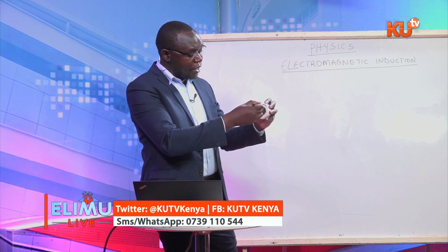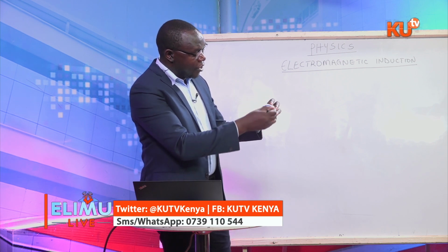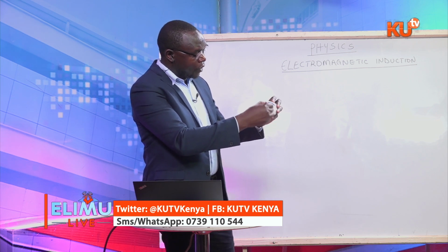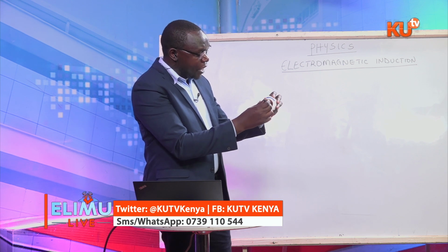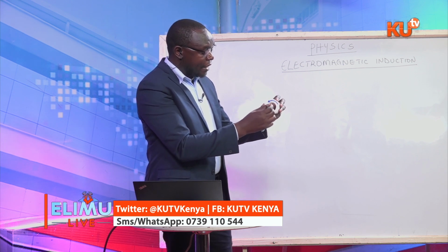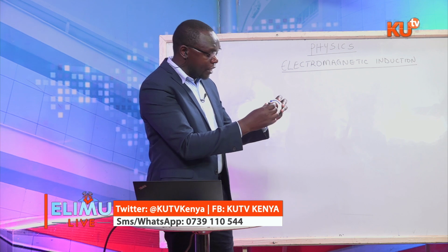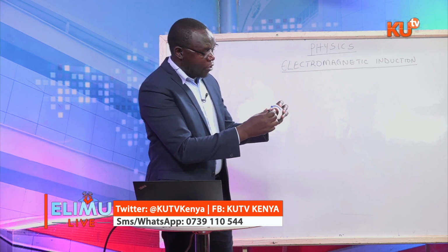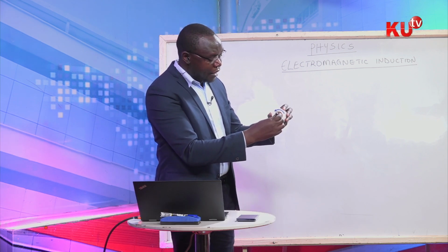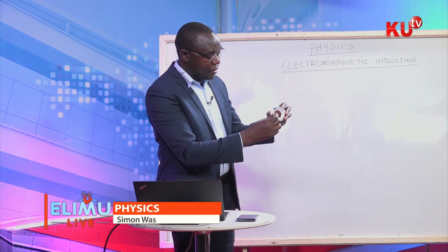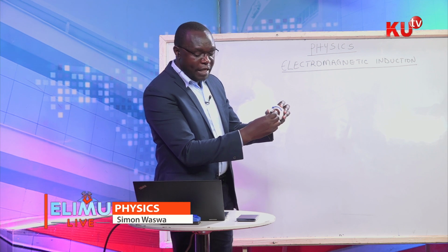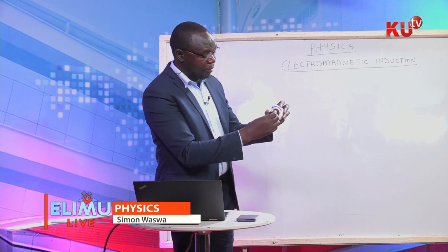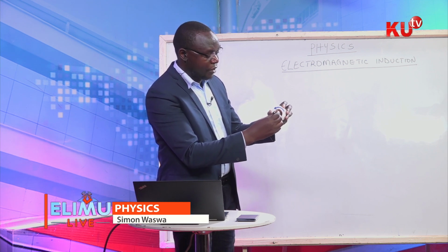The flow of current in the anticlockwise direction causes this face of the coil to acquire a north pole. And so, as one moves the bar magnet into this end, it resists that magnet from entering the coil. Now, when the bar magnet is made to rest in the coil, there is no induction of mechanical energy into the coil, and so no charge flows. That means no current is induced in the coil.